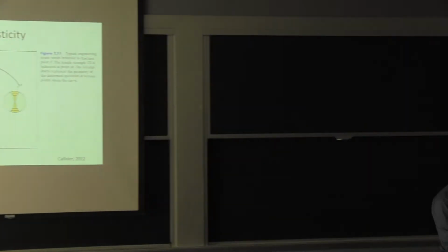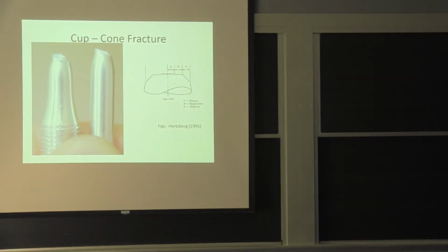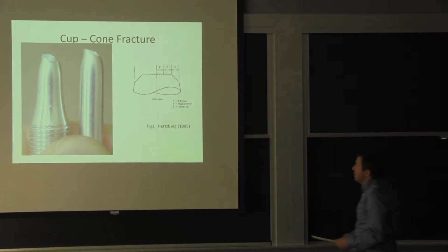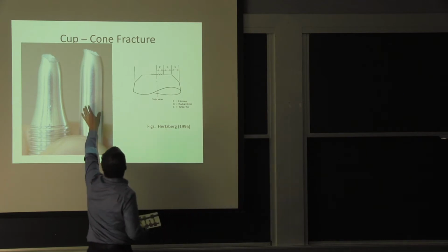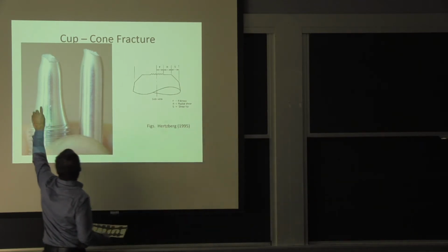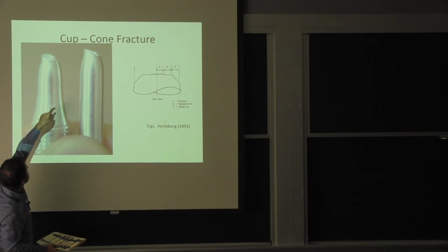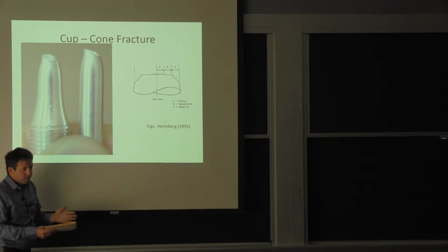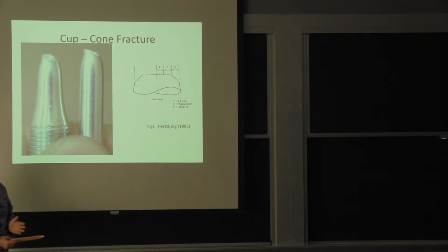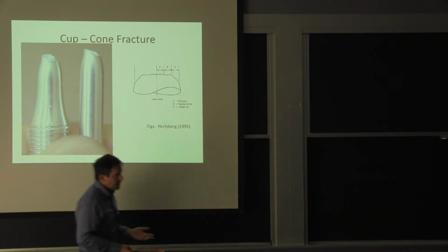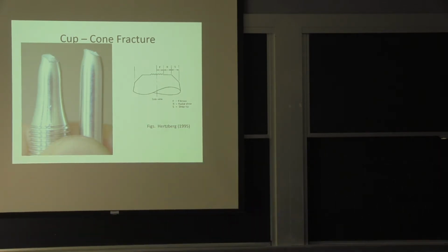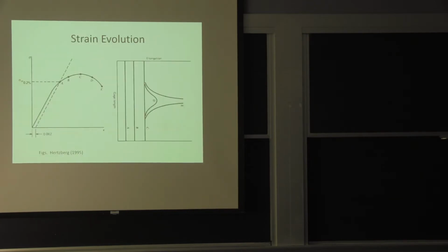Okay, so going to the necking process, you can see it on essentially a bar that was originally a certain diameter. It was deforming already, so this has been deformed. But you see the curvature, you see very close to the fracture surface, these are matching with each other. Very close to the fracture surface, you have this local effect where you reduce the area. And again, it's not something that's taken into account in the stress-strain curve. So what happens in that reduced area? You have more strain, right?